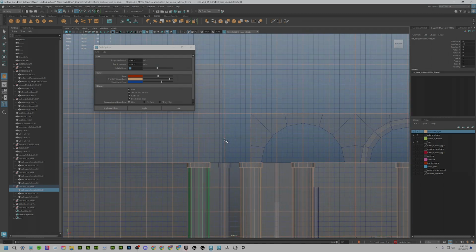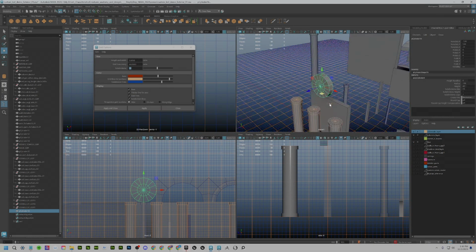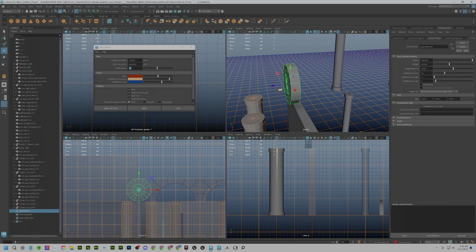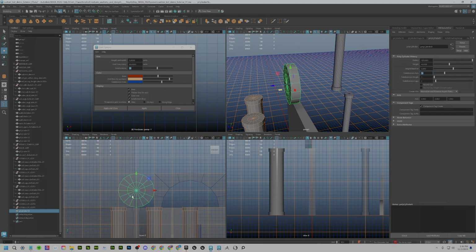We could go in here and do that. I start off in the middle here and just drag out so that it hits right there, and then let go and then push up. And if I had it in a better one, we could check the attributes on that, and you could just manually enter this, of course. 16 is the magic number for radial, so it's all 4-sided, divisible by 2, goes down from 8 to 4 to 2, and powers of 2, which is really nice.